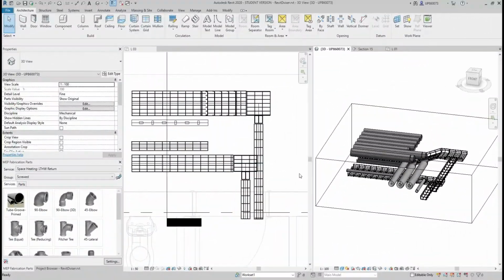Once this bit has been modeled, then you stretch the services as per design and schematics, and wherever possible, you copy what you've done to speed up the process. Although this project is not too complicated and clashes can be spotted in Revit, I normally export it into Navisworks anyway to check for clashes. Again, you model a certain bit of the corridor, export it into Navisworks, check for clashes, then again model, export and check. I haven't done a clash detection test for this project as it's not too complicated. I just did a fly-through, which should be enough.